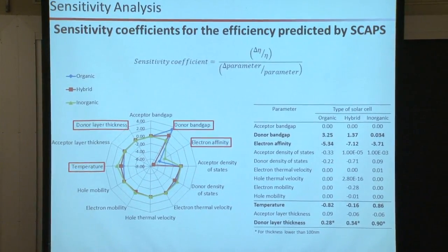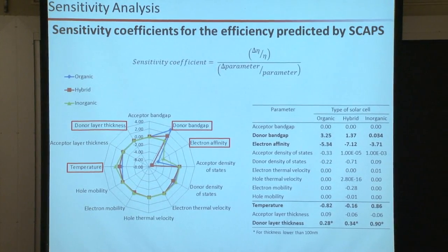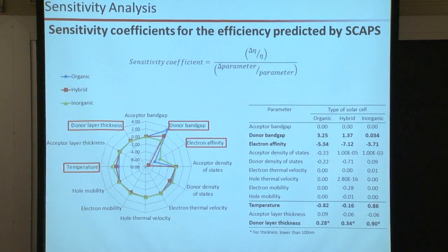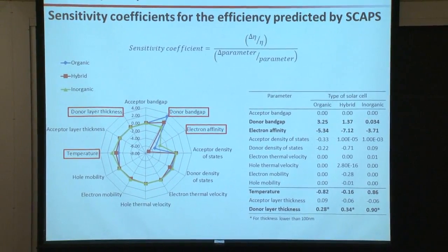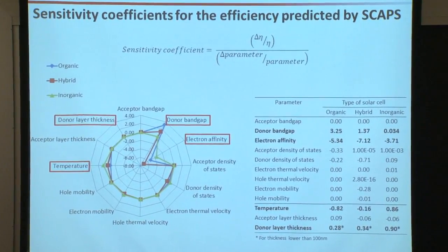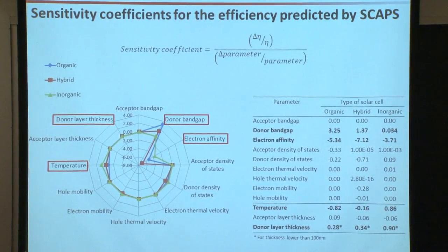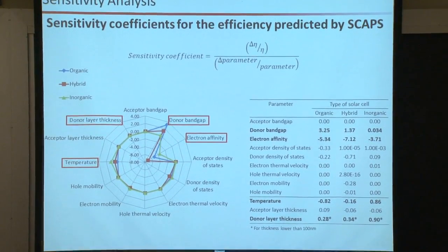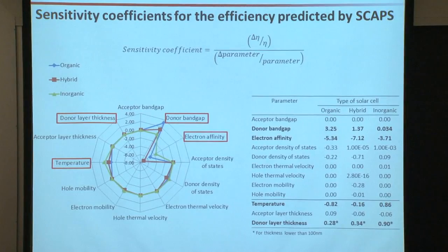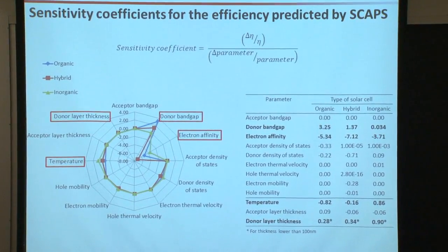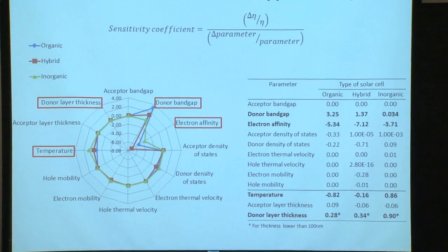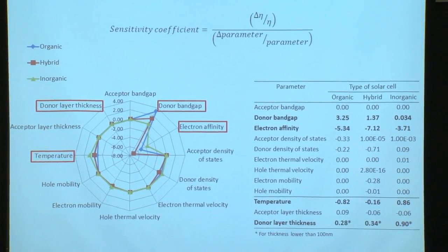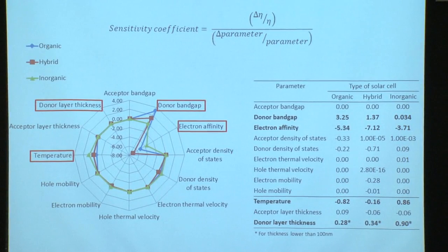To determine the critical parameters which influence the performance of the solar cell, we calculated sensitivity. Sensitivities are calculated from the change in efficiency observed by varying simulation parameters or material properties. They were expressed in terms of a 1% change of the parameter relative to its base value.